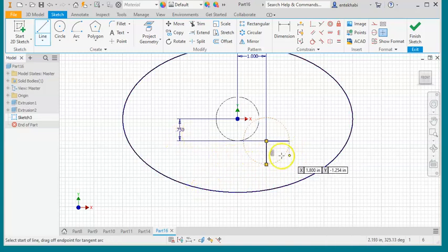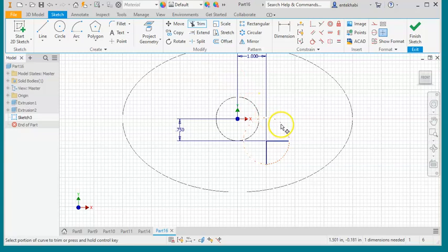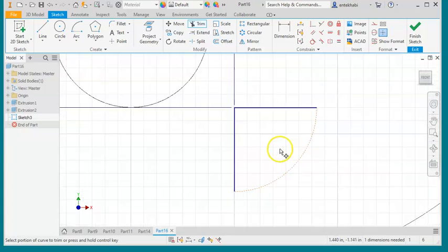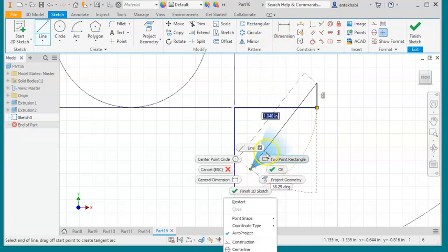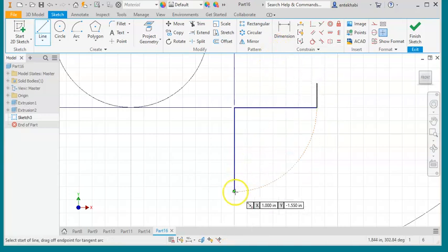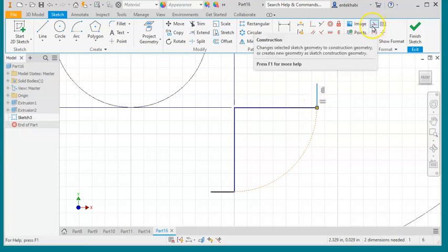This would help us define the location of this adjustable hole. So let's trim the circle, and we will use this arc by adding 2 more short lines to the end of this arc, with another one similar on this lower left corner. Make sure that these 2 lines are equal, and also these 2 lines should be selected as construction lines as well.